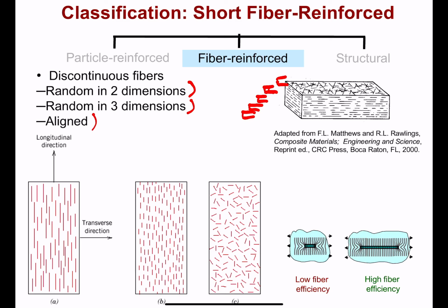So we would therefore have randomness in the fibers within each sheet in the plane, but there would be very little randomness across the height of this structure, where most fibers have to be located within the plane from which they were once fabricated to build up this sandwich structure. So that would be a way to realize a material that's random in only two directions, but not all three directions, as the z dimension here would not be random.